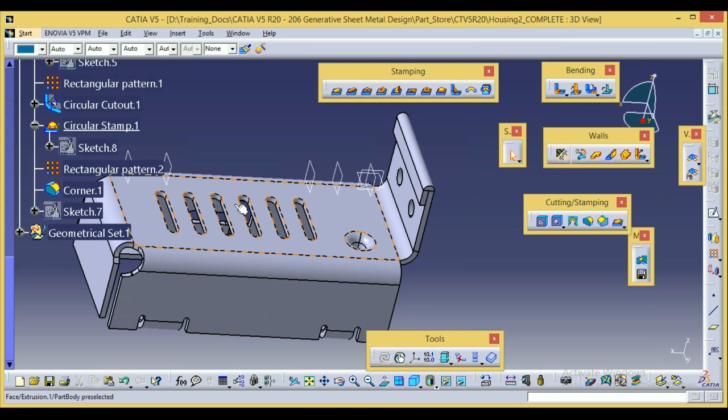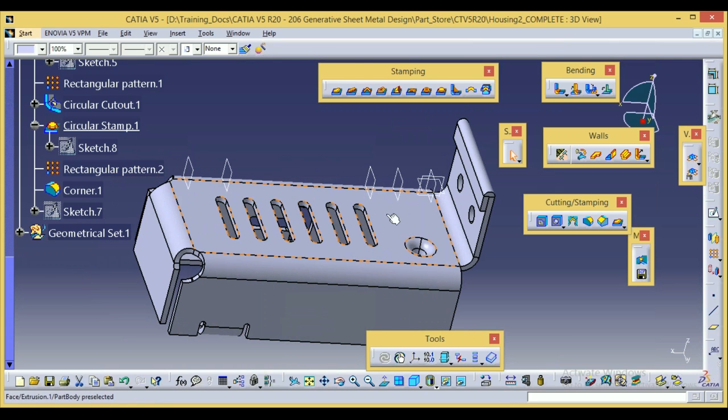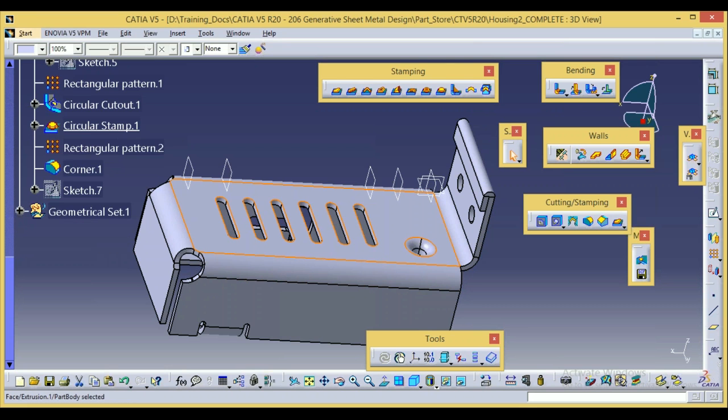Imagine if only this face is a flat sheet, you make a bend here and another bend here, like a Z. When you give the bend, its strength will increase and it will become very stiff. So in sheet metal, when we add bends, it becomes stronger. That is one of the reasons for giving bends, and the main concept of making sheet metal parts.